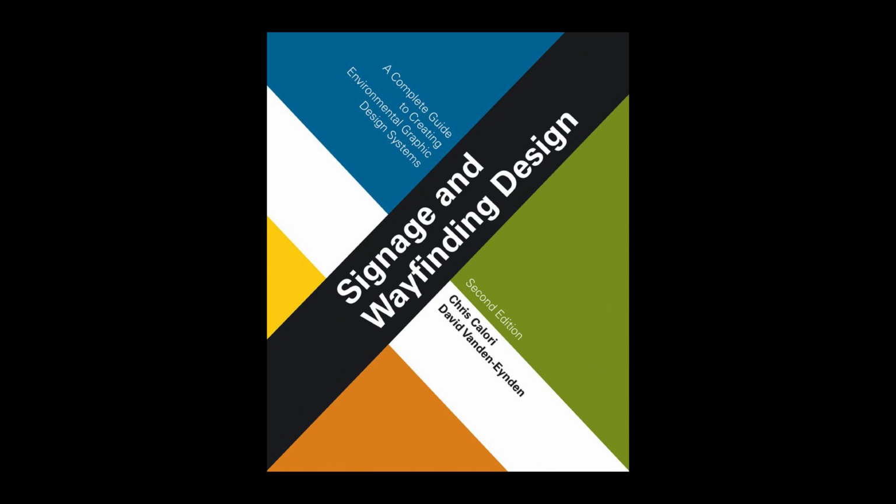Recent developments in signage application of porcelain enameling allow graphics with an improved degree of resolution and tonal range, as well as wider color ranges. Although exact color matching isn't always possible, porcelain enamel coatings can range from transparent to opaque, but opaque colors are typically used for signage. The gloss level of porcelain coatings can range from high to low.